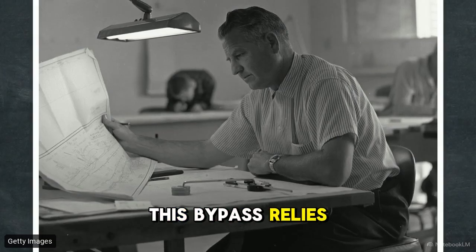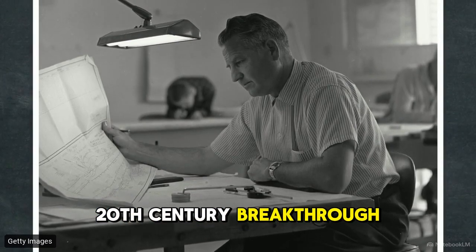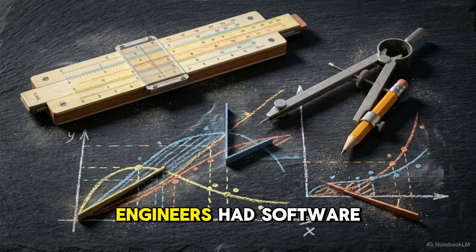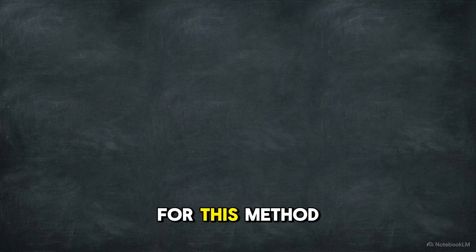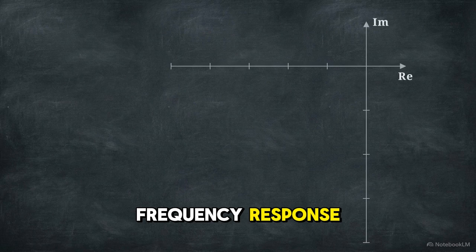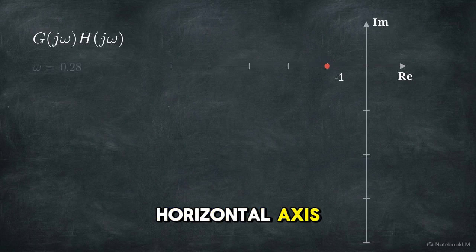This bypass relies on the work of Harry Nyquist and his mid-20th century breakthrough in mapping dynamic stability, created long before engineers had software to brute force the math. The playing field for this method is a two-dimensional complex plane. Here, we map the open-loop frequency response, G(jω) times H(jω), placing its real part on the horizontal axis and its imaginary part on the vertical axis.